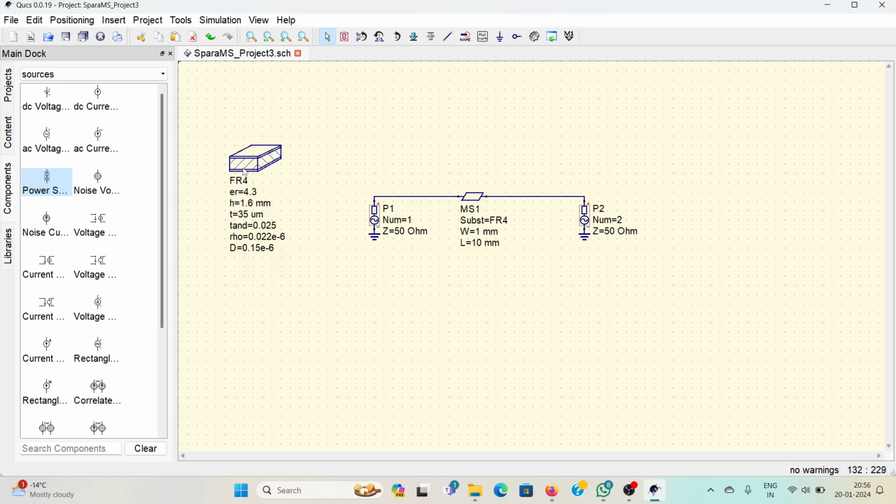We will have some dielectric loss because of the loss tangent of a dielectric. If it's more lossy, you are going to have more attenuation in the signal traveling through this kind of a microstrip line. But for now, let's go ahead and set up the same simulation as we did before. So we kind of made a matched system. We match the entire impedance of the system, 50-50-50. So let's go ahead and do that.